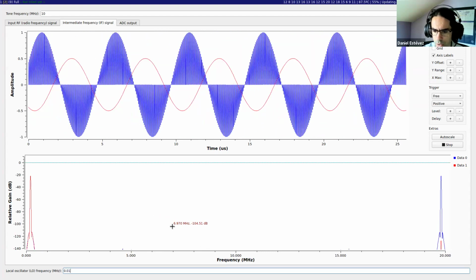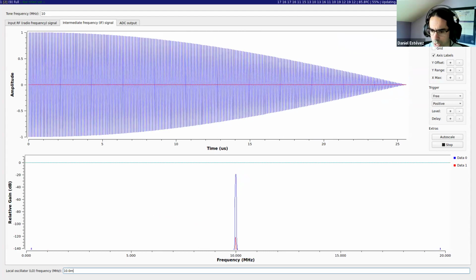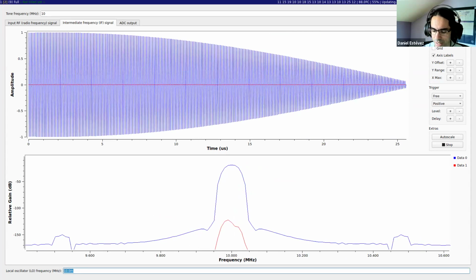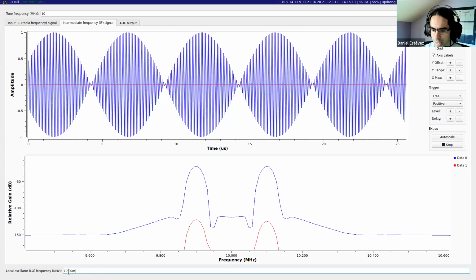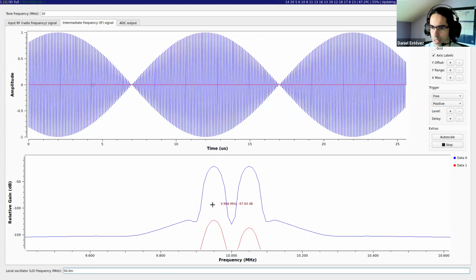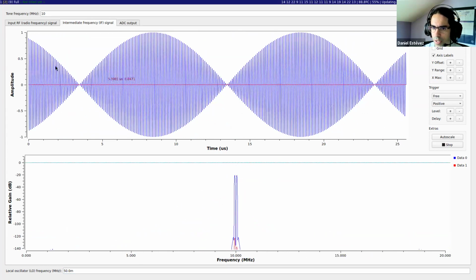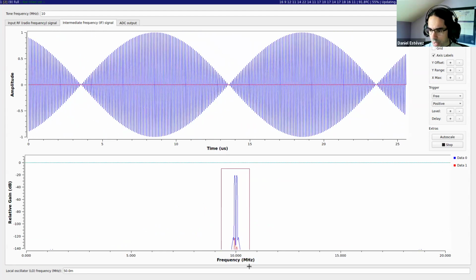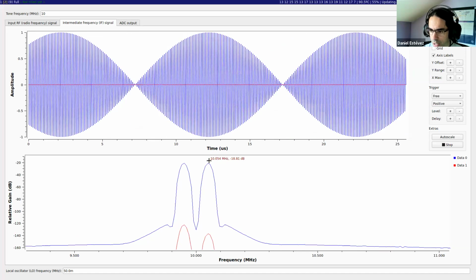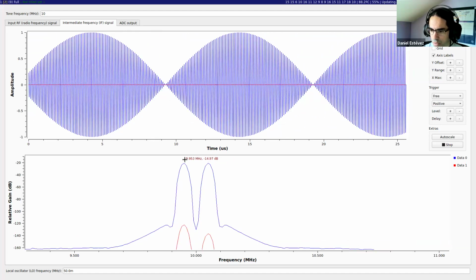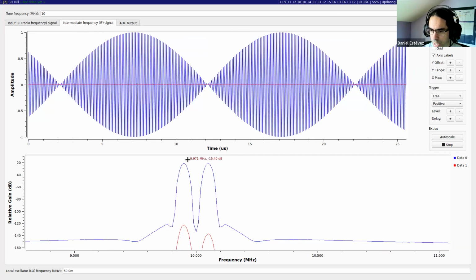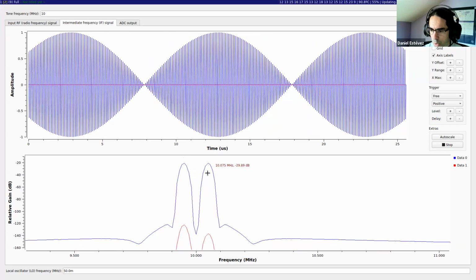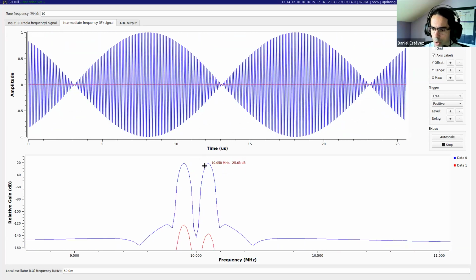doing what? By doing a very low frequency here, maybe not as low because now the two frequencies are so close together that the FFT doesn't have enough resolution. So let's do something like this. If we only want to shift the 10 megahertz signal by 50 kilohertz, then we get something at 10 megahertz plus 50, something at 10 megahertz minus 50, and having one filter which is capable of letting one of these copies pass, let's say this one, and attenuating this one is complicated.